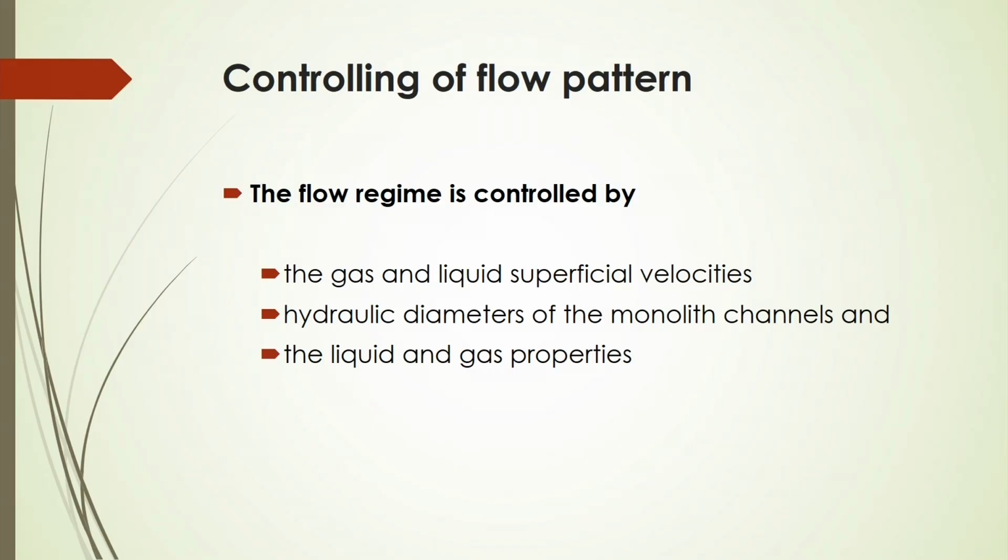Now, how to control those flow patterns? The flow regime, sometimes called the flow pattern, can be controlled by the gas and liquid superficial velocities, the hydraulic diameters of the monolith channels, and the liquid and gas properties.